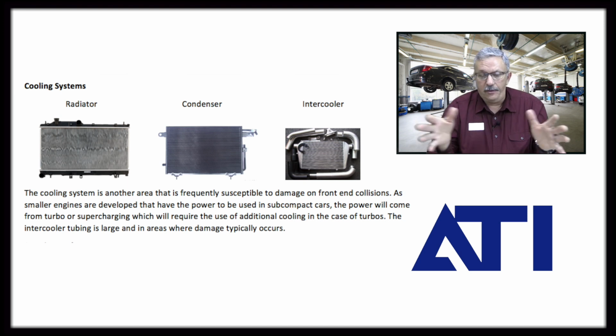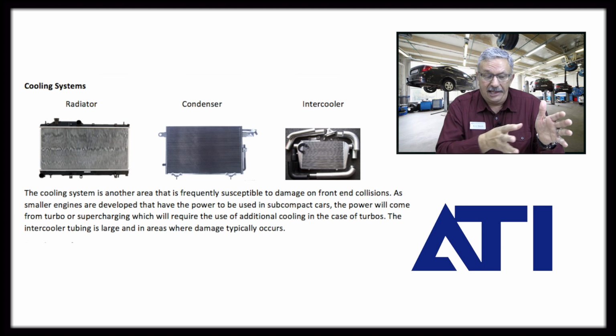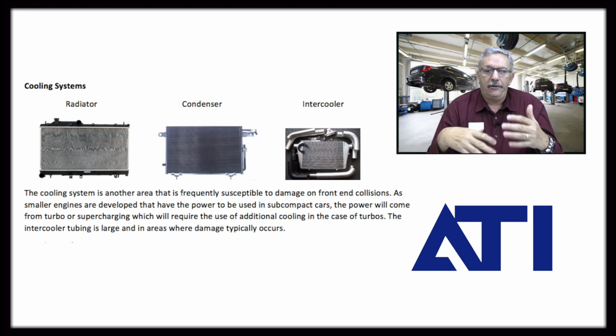Then when the repair is finished and I go through the scan process, I want to turn that vehicle on and I want to inspect it while the vehicle is warm and under load. And rev the motor a few times, let the turbo kick in, and then check and see if I've got leaks. Those are things that if we look at road testing the vehicle is something we can charge for.